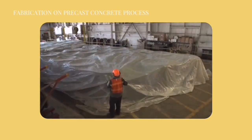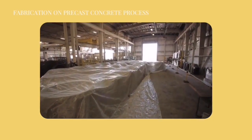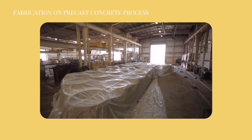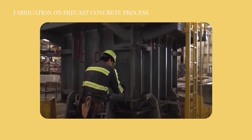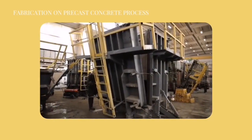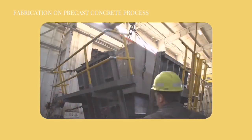Once the QC technician confirms that the product has reached the desired strip strength of 2,500 to 3,000 psi, then the stripping process may begin. This involves opening the outer jacket, collapsing the inner core, attaching the lifting devices, and removing the product from the form.